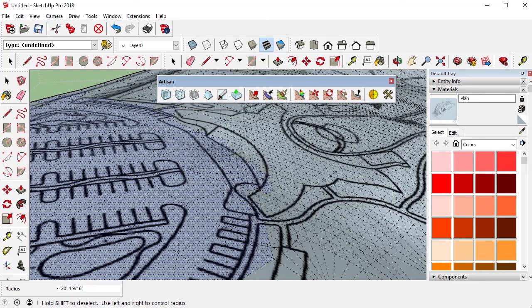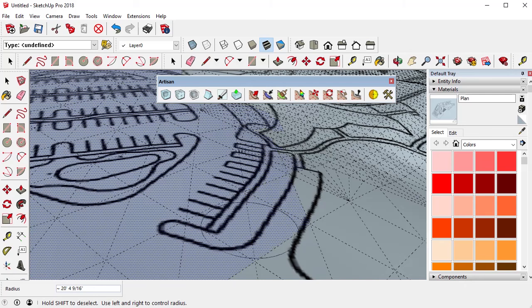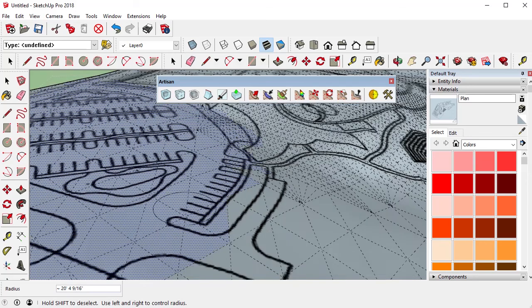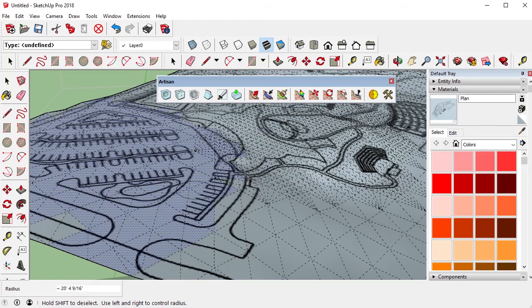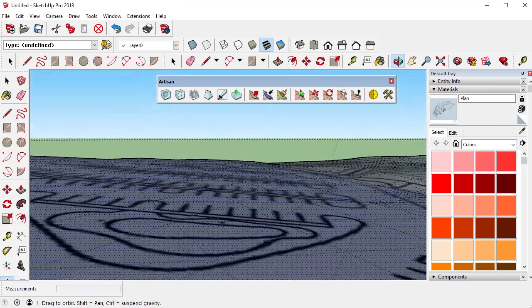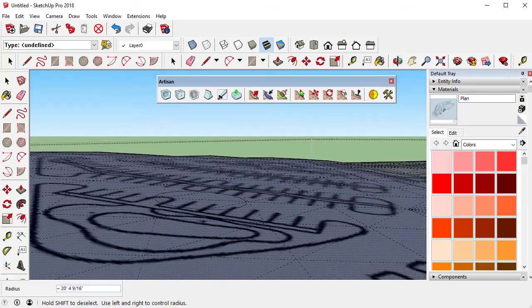All right, I don't want to take a lot of your time here. The idea is that we're just making this smoother. And I just messed that up. Grab those out, reselect that in. All right. This area here is going to get more detailed later, but let's go ahead and make that planar, make that best. And what that did is it just adjusted that whole parking lot, so that parking lot is now a little bit more flat.